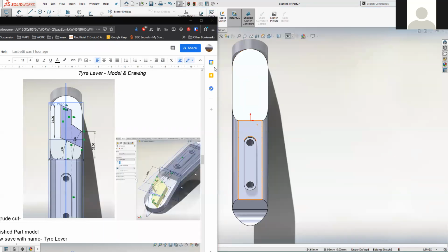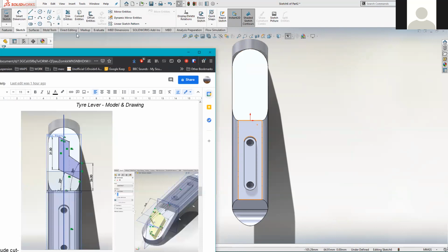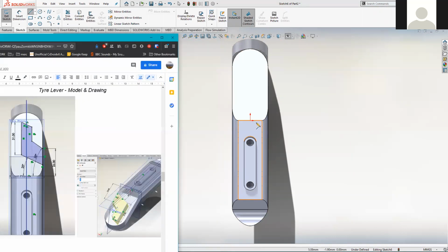which is hard to rotate in your head as you're drawing. So what are we going to do first? Let's get the line tool. So line tool there. Let's pull that off to the side a little bit. And then we're going to sketch out this rough shape. We don't have to be too accurate with it to begin with, because we're going to add dimensions and add relations to it just to get it looking as it should be. So I believe the first point is locked to.